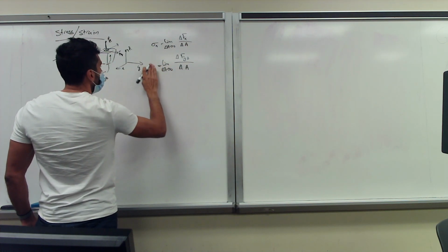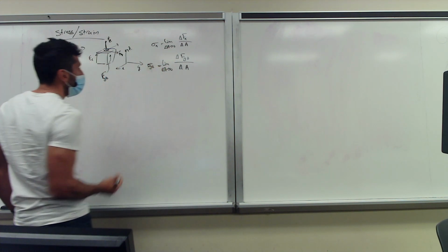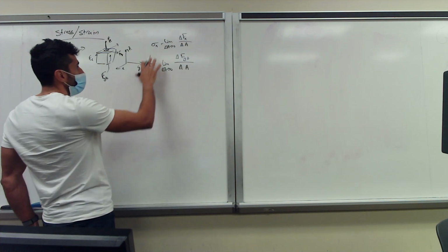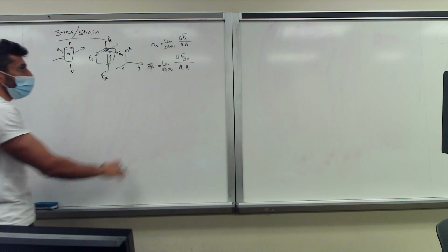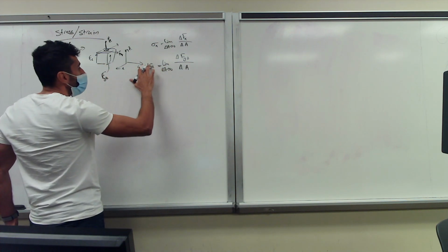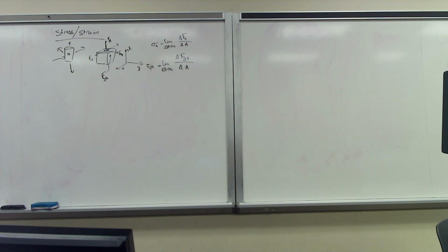This is what we call, again, shear stress, and in this case it would be YZ. And what we do in convention style is, for the direct stresses, that's your X, Y, and Z forces in the direction of X, Y, and Z, we use sigma, and for the shear forces, we use the Greek letter tau.